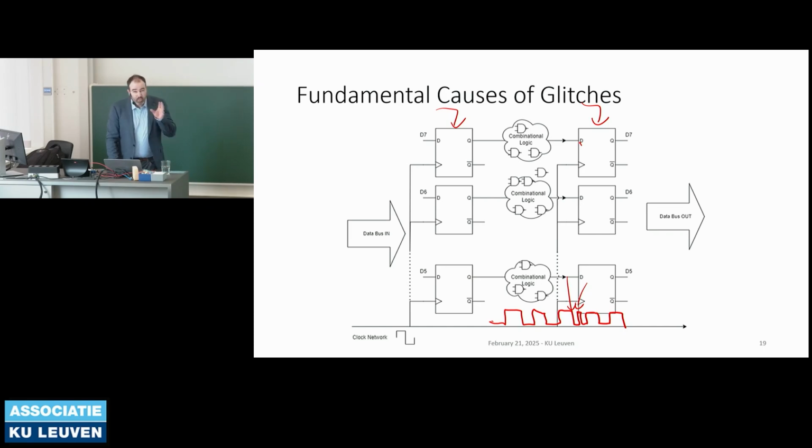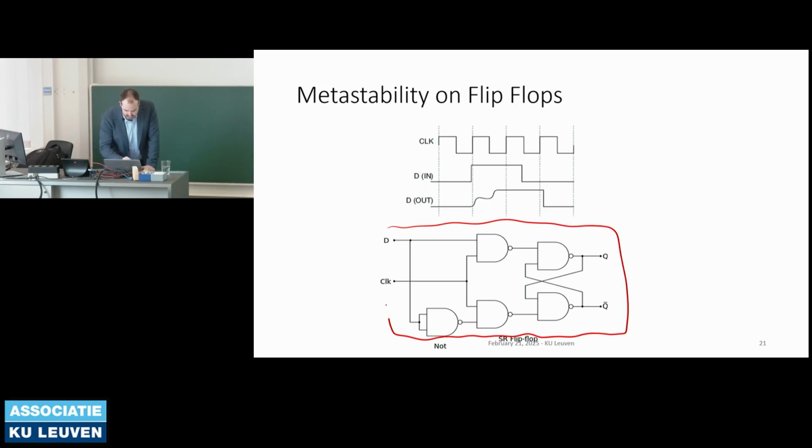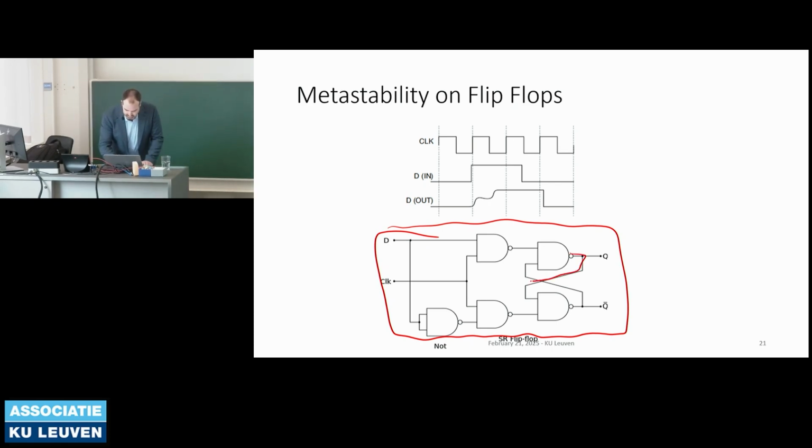It gets even a little worse than I described there, because there's this issue called metastability with flip-flops. With metastability, the internal construction of flip-flops actually has this sort of feedback method where we have basic NAND gates. The output feeds back into the other one.